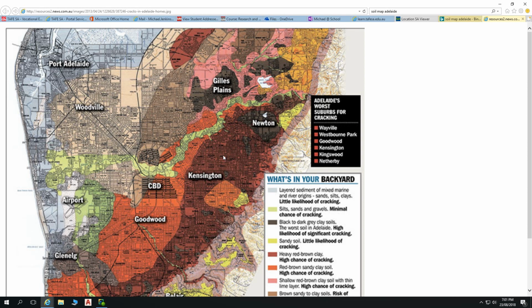I'm going to scroll up a little bit. But also, strange enough, people who live in old cottages around here, the Unley Parkside area, have massive amounts of movement, like cracking in all these walls. But further on down, you've got buildings built in the 60s and the 70s which don't display any movement, sitting on exactly the same soil. The difference is footing technology that has changed.